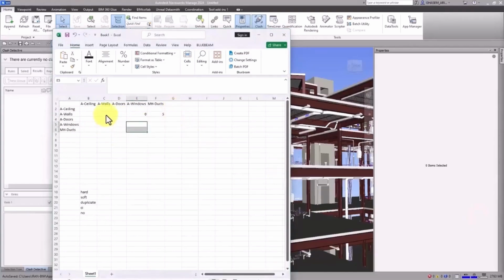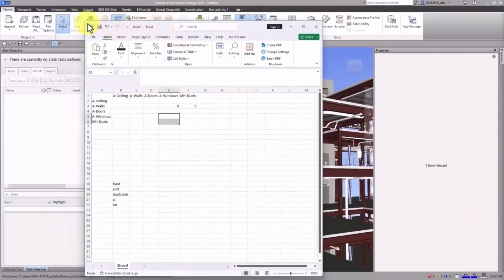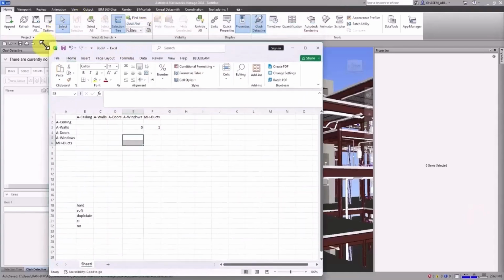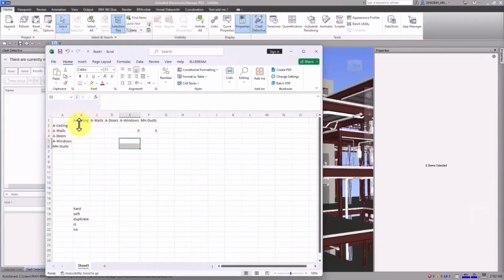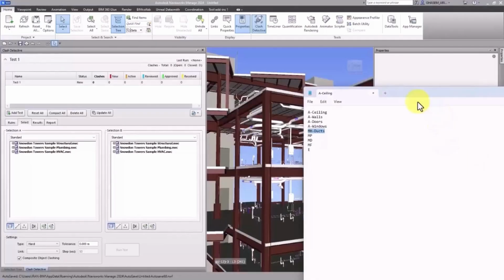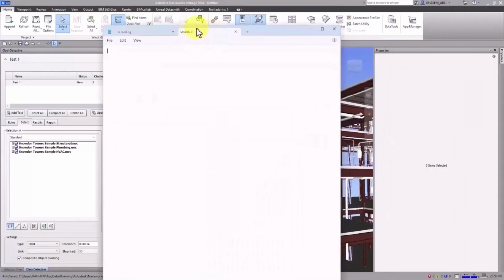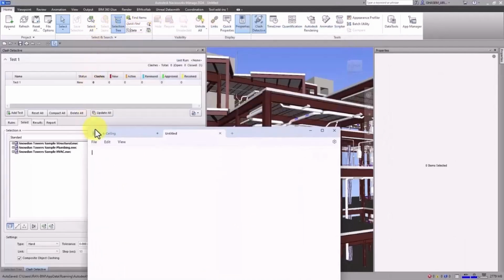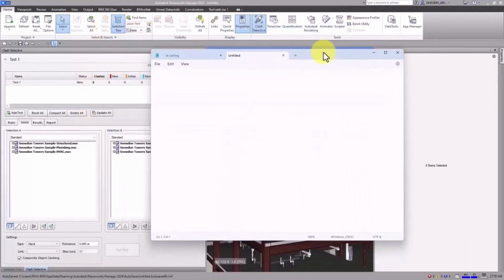So it's necessary to have a clash matrix, and in this way you can have professional control of your clashes, especially when you want to create clash sets, which you will see. It will be helpful. Okay, now we want to describe all of the clashes. And here I should tell you that you need to define the level of your clash in your contracts, which we have LOC for.